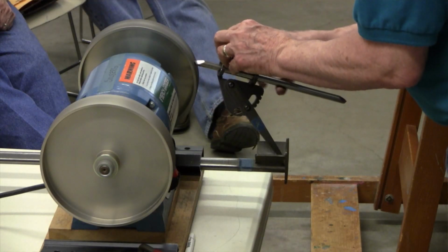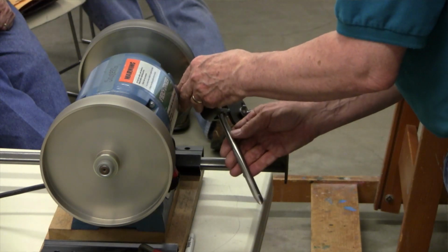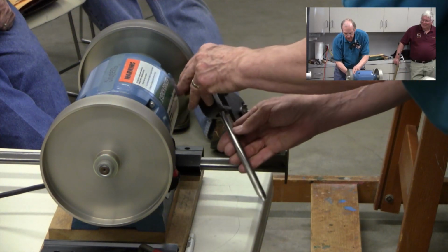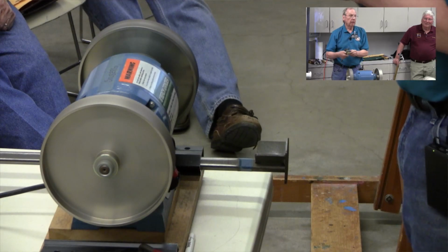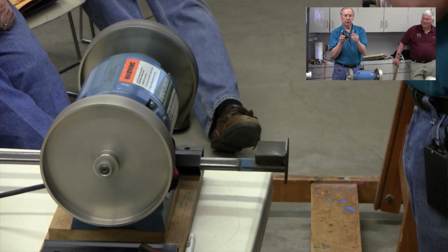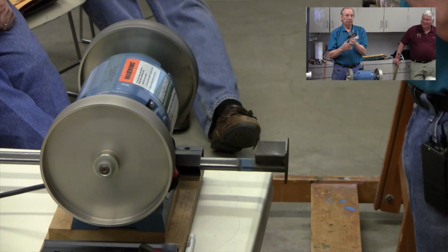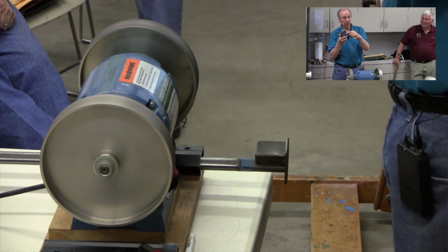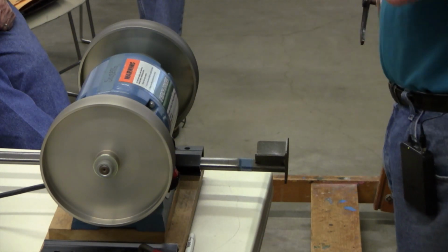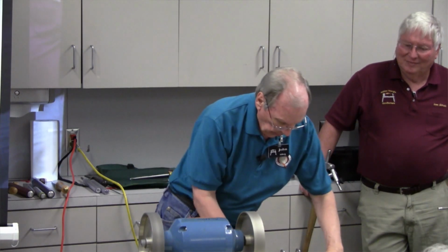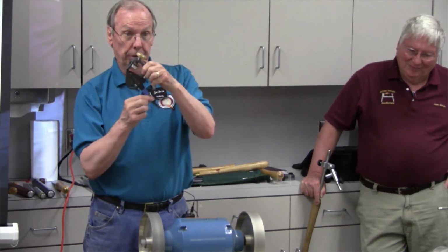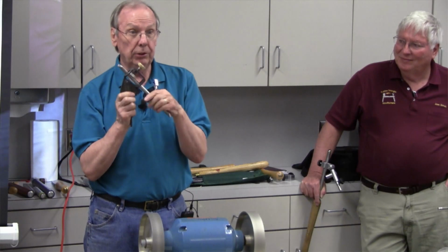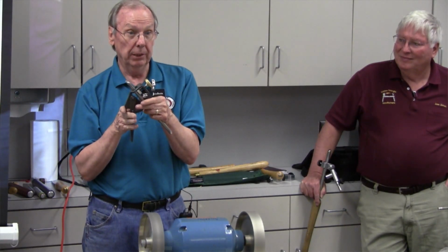And now I'm going to make sure that I get the side grind sharp as well as the tip. So I'm just going to rotate this back and forth. So John, you set it up with just the very front edge, and then by rotating it, your side edges come in automatically. That's correct. Now I can change the side edge angle if I want to, by readjusting where this grind lever goes. But I've set it up on this one and locked it in place so it's always uniform, the same every time I sharpen it.